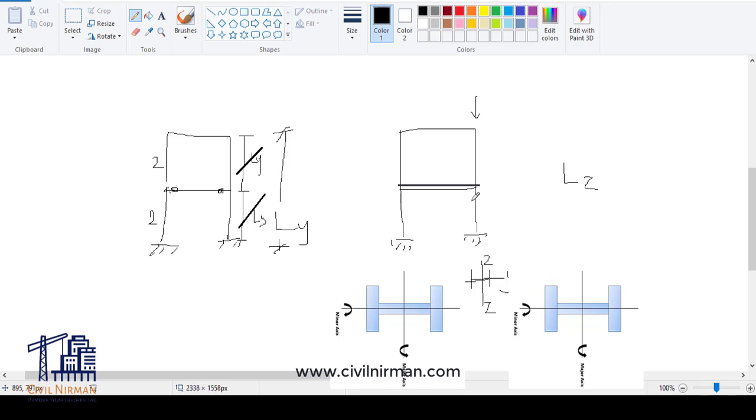So in this particular arrangement, my Z, the major axis, is connected with moment frames. So here again, if this is an individual 2 meter, then I'll be considering my Lz as 2 meter for the top portion, and in the bottom portion again that Lz will be 2.